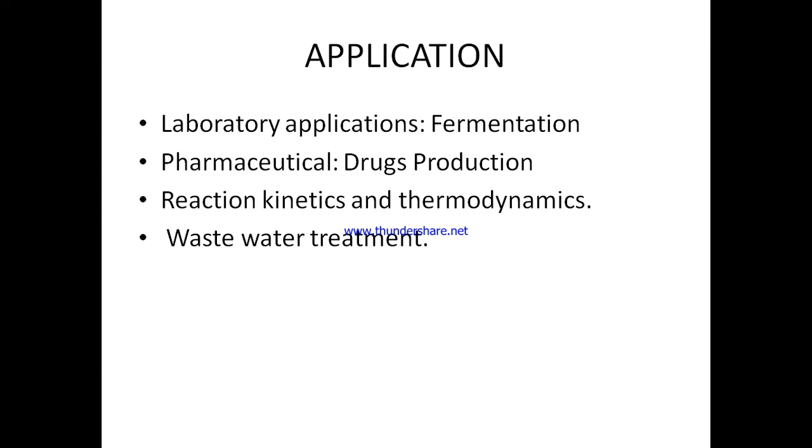In the process of scaling up industrial operations, either you want to use a stirred tank reactor later on, or a plug flow reactor. The interesting thing is that you can use batch reactor to obtain the design parameters, the kinetics of the process and the thermodynamics. You can get that through a batch study, and whatever results you have can be scaled up to the commercial large scale with several other contacting patterns for the process.